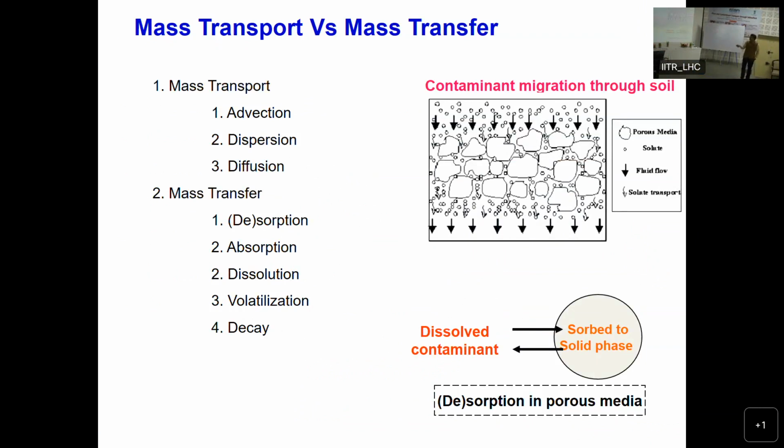dominant. And then dispersive, mechanical dispersion is because of the presence of the soil particles, because of velocity variation and also because of the tortuous paths these molecules are following. So the contaminant plume is going to disperse along the flow direction and also transverse to the flow direction. That is the mechanical dispersion. Molecular diffusion is taking place because of the concentration gradient difference. So let's say at some place the contaminants leak and they move towards the surrounding location from the high concentration to the low concentration. So combining these, advective, dispersive, and diffusive transport mainly govern the contaminant transportation.